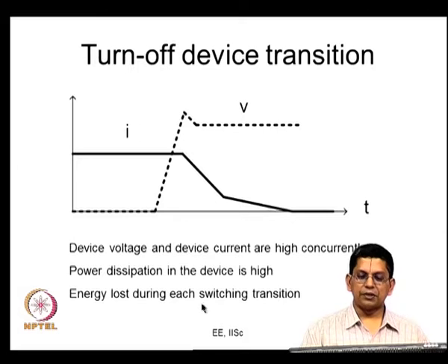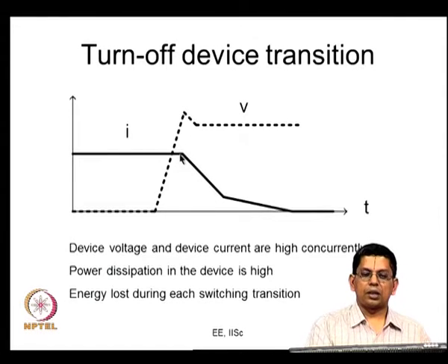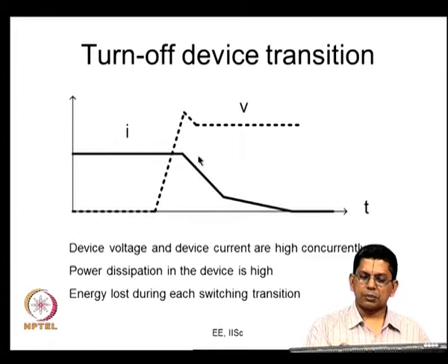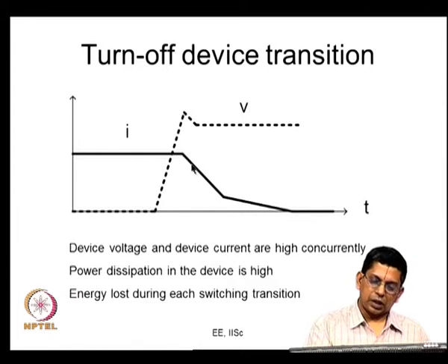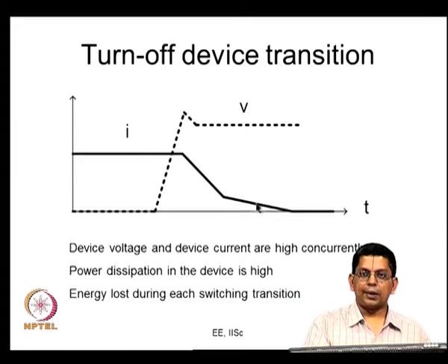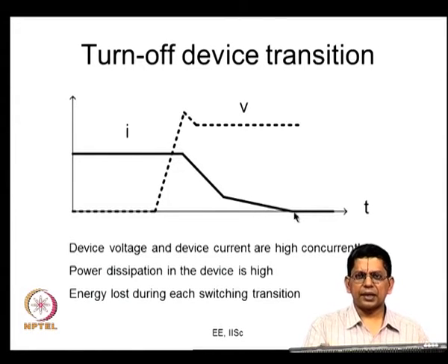So similarly, let us say the device is turning off. It is conducting some current and that current falls when it is turning off. It may fall rapidly, and sometimes it may fall rapidly initially and then slow down. So it is more gentle than this, and sometimes you can represent that as a double slope. That is, the current, instead of falling sharply all the way down, initially falls sharply and then slowly tapers down. So this part is represented like this, asymptotically, like two straight lines for the purpose of convenience, and this is sometimes called tail current, TAIL, tail, because it is like a tail.